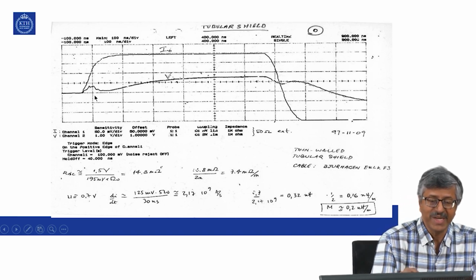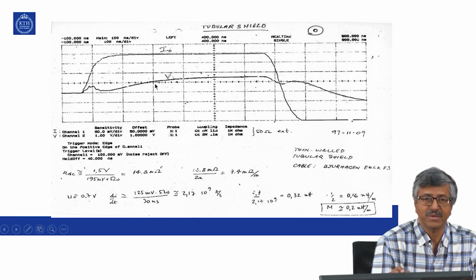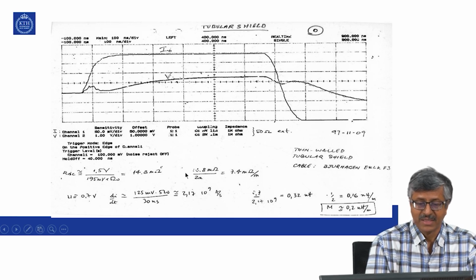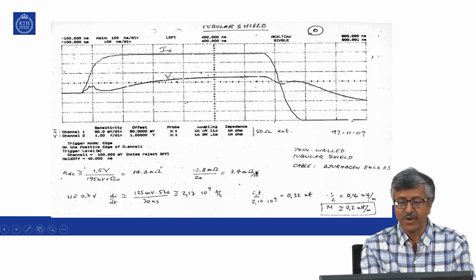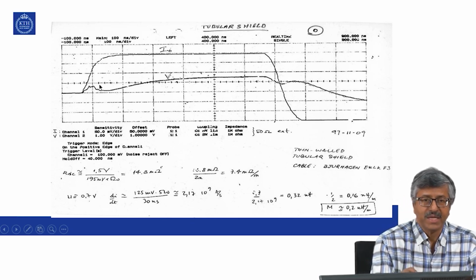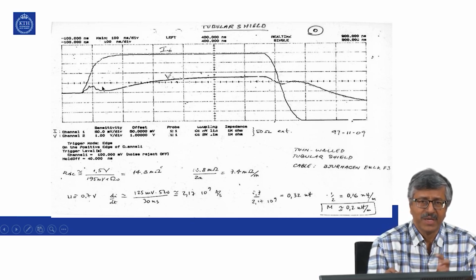Even though it is not intended as a shielded cable, due to the fact that for keeping away moisture you have aluminum foil, a solid shield, it has a very good performance, and its DC resistance is only 7.4 milliohms per meter, and it does not have any holes.